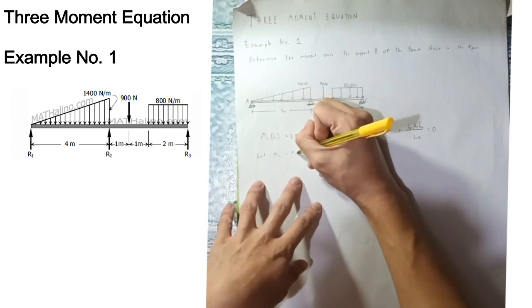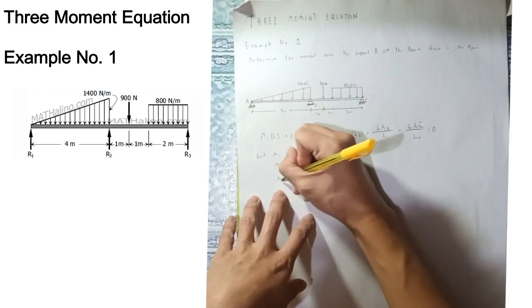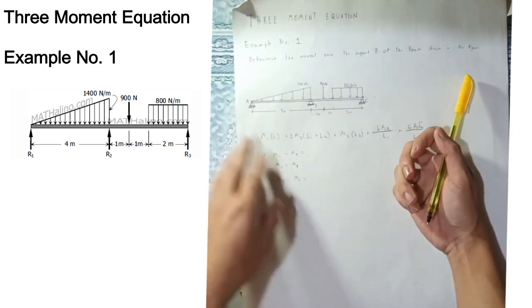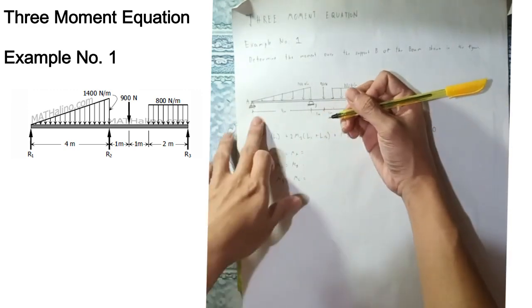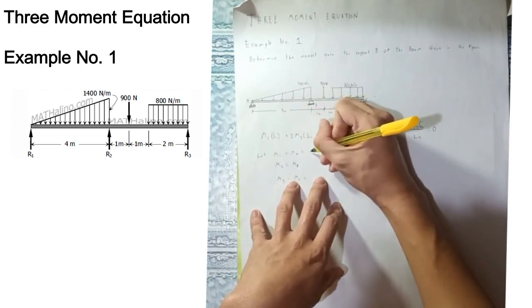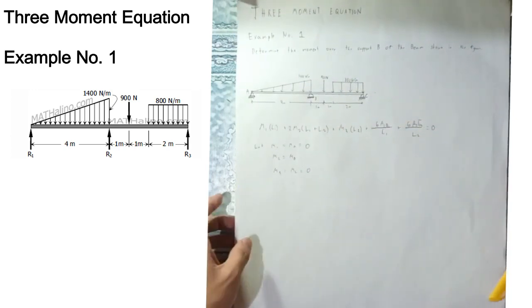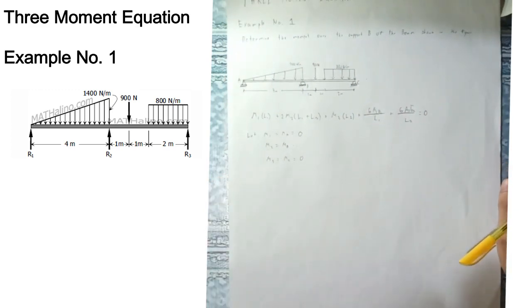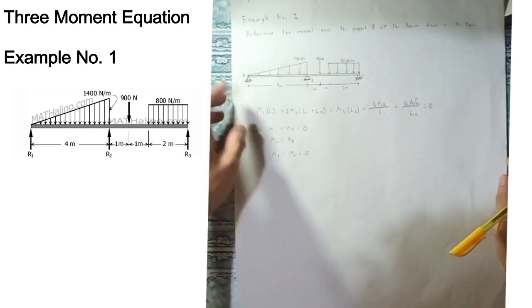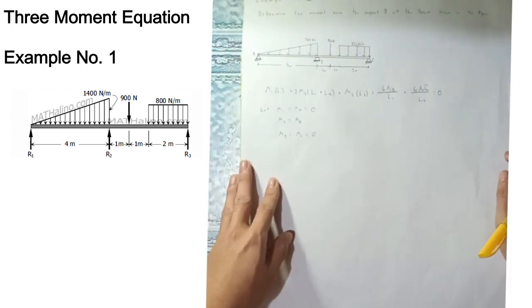So let M1 equal MA, M2 equal MB, and M3 equal MC. M1 is a hinge, so the vertical and horizontal forces are reactions and the moment is 0. Same with the roller, C is 0. First, side A, side AB, let us solve that first.